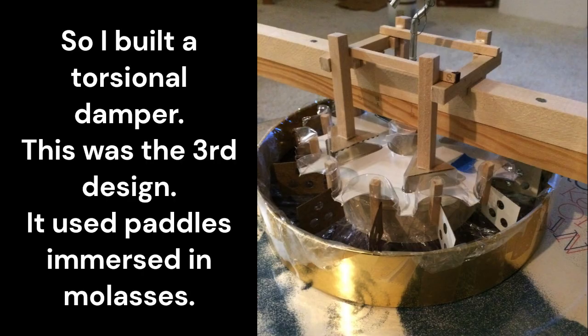So I built a torsional damper. This one pictured here was the third design I tried, and it used these 12 paddles that were immersed in molasses. The idea of a damper is to allow motion, but to resist the speed of the motion. So anything that's moving, it'll give a resisting force to that motion. But the slower the motion is, the less force the damper applies.